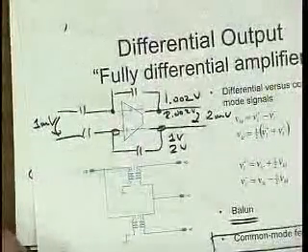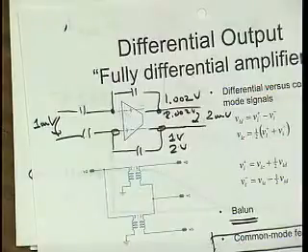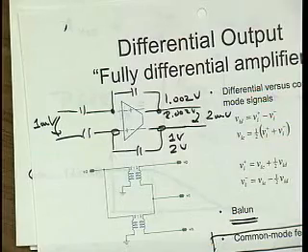When you build a single-ended amplifier, that's much harder, because there really VDD is changing, and you have some capacitive coupling through your current source that otherwise, of course, shouldn't couple the voltage through, and so you get a much poorer power supply rejection ratio.